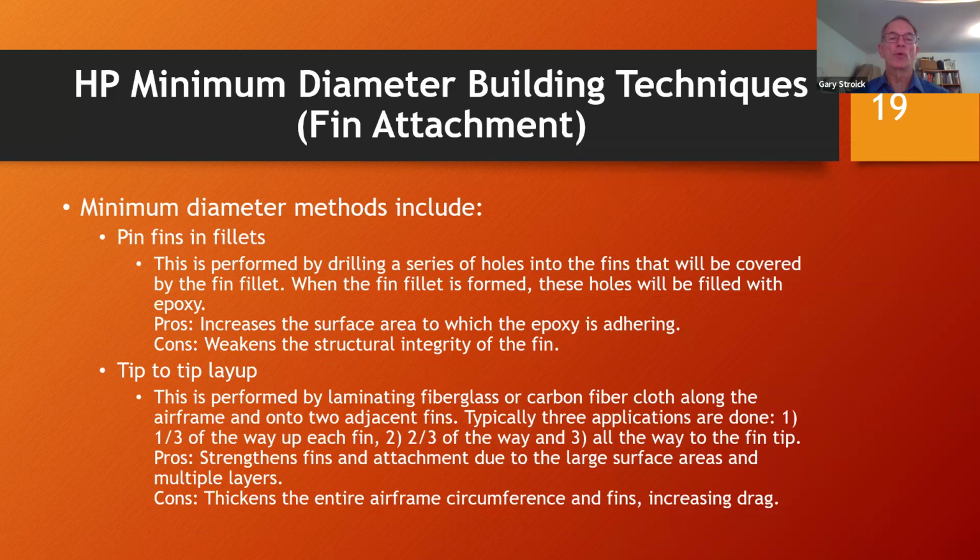Another way that's used more often these days is what's called a tip-to-tip layup. And this is taking your fin, attaching it to the airframe, generally with a fin fillet underneath, or basically along the sides of the fin as you normally would. And then once that epoxy is cured and the fin fillet's fully formed the way you'd like it, between two fins on your airframe, if you have a 4-fin airframe, let's just say each fin is 90 degrees apart,